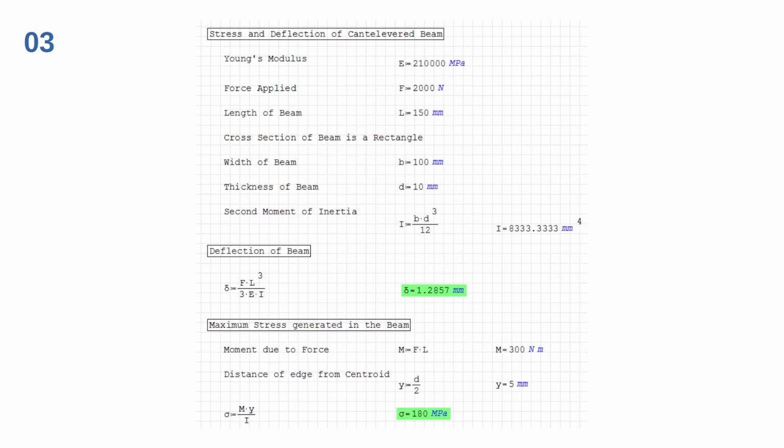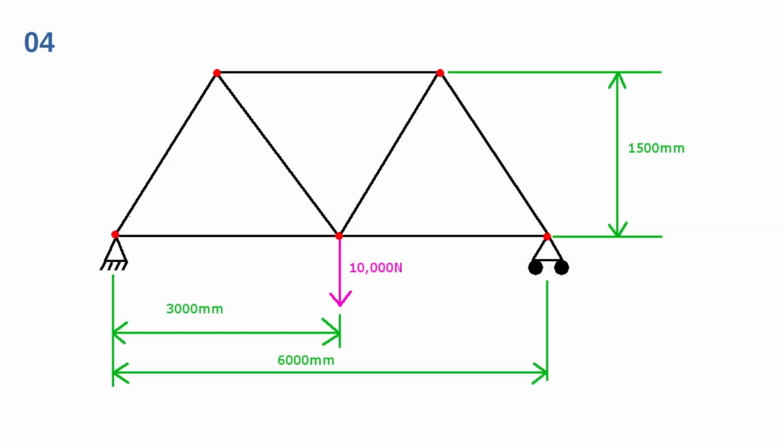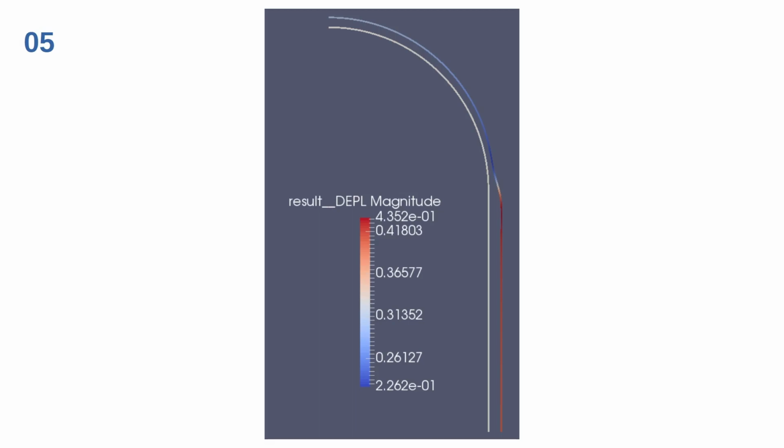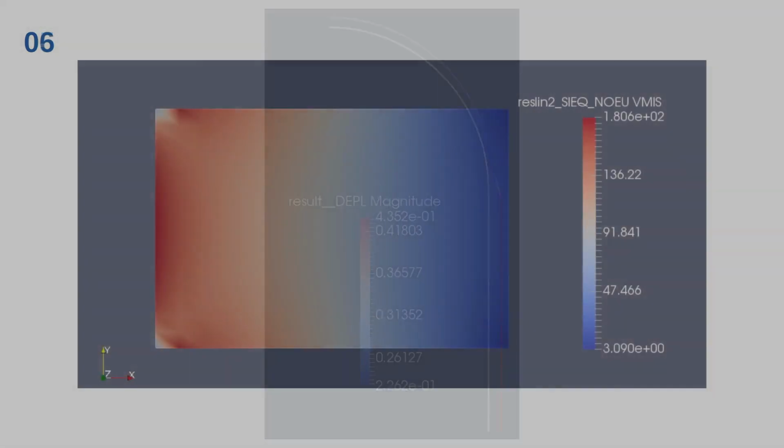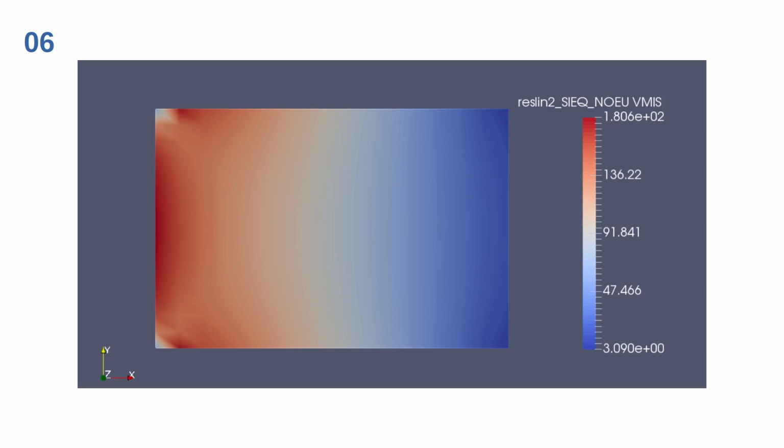with hand calculation. Then, we are going to take this one-dimensional analysis and conduct a two-dimensional analysis using beams. When geometry is cylindrically symmetric, we can use axisymmetric mathematical models and conduct finite element analysis, which we are going to see next. In several cases, when the third dimension of a structure is very small compared to the other two dimensions, we can conduct finite element analysis using shell elements.